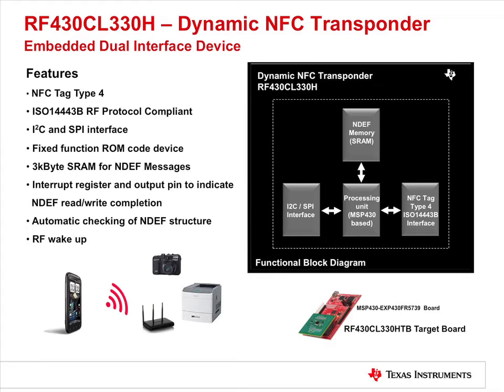The integrated SPI or I2C serial communication interface allows reading and writing of NDEF messages into the integrated SRAM, and the NDEF message can be accessed wirelessly via the integrated ISO 14443B compliant RF interface, supporting up to 848 kilobits per second.